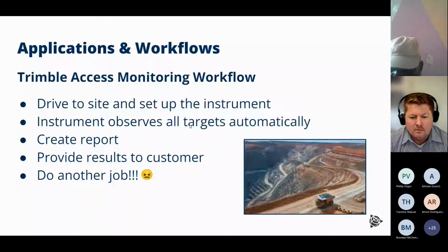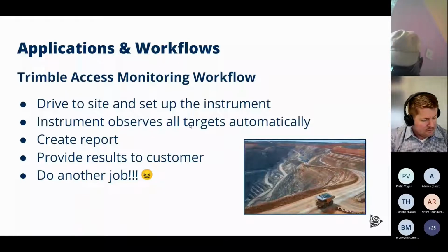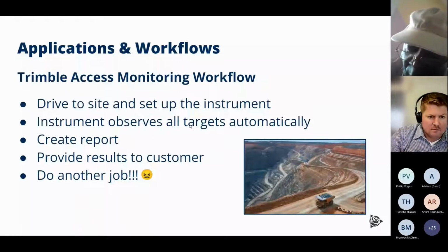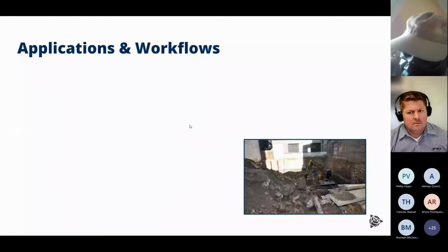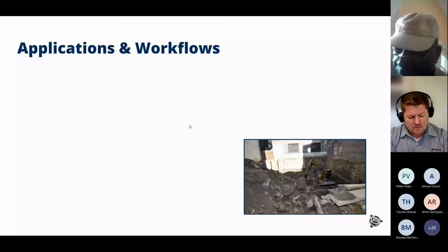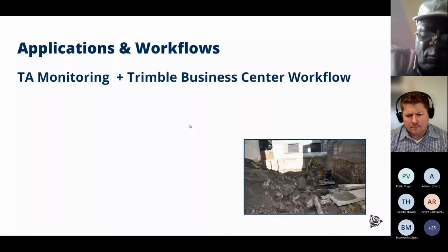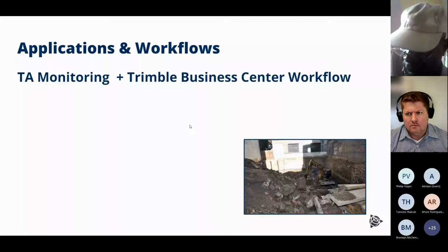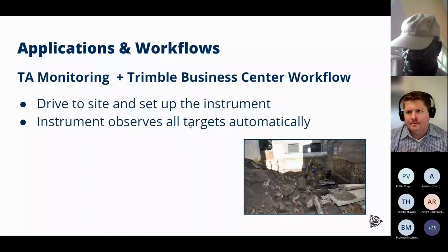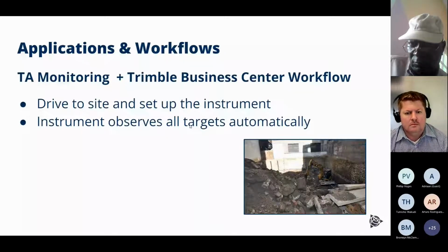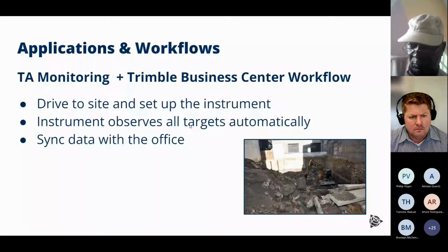Some of you probably are using a Trimble office software, which is called Trimble Business Center. So there is a way to connect both workflows. Again, when you're using Trimble Business Center, you would go to site, set up the instrument. You would set up the instrument to observe all targets automatically, and then you will not create a report on site. You will sync the data with the office.